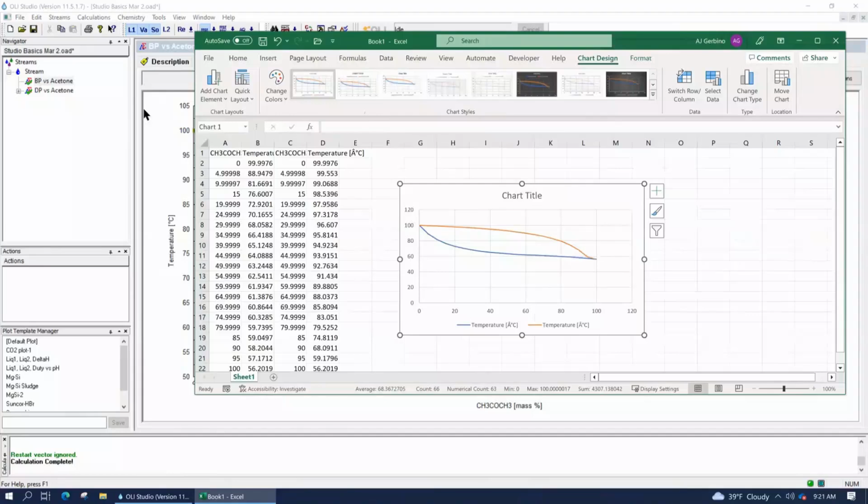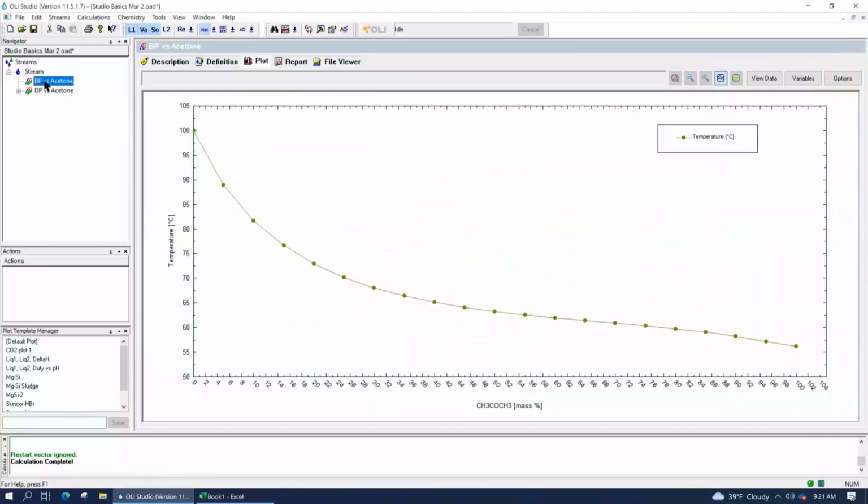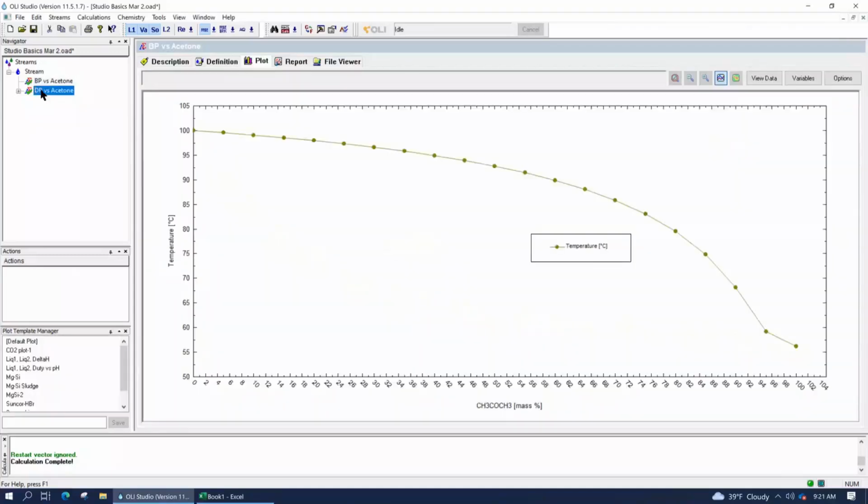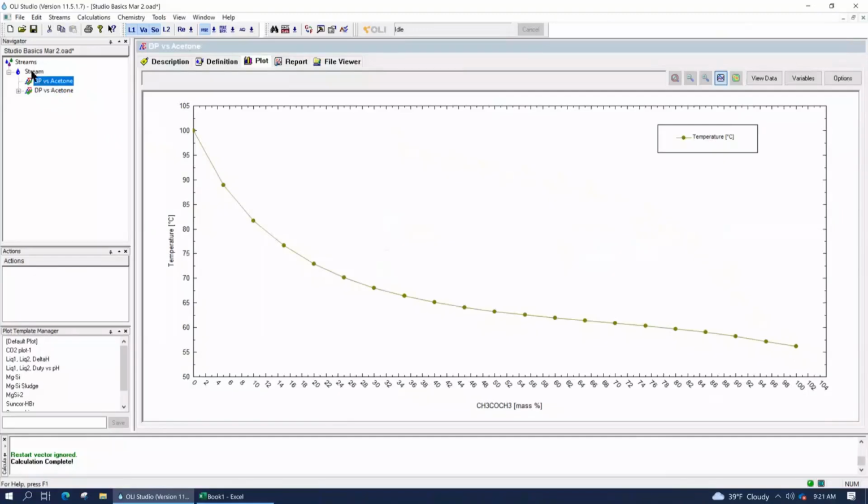Okay. So the teaching point on that was that one, you can create phase diagrams, binary systems, even ternary systems if you need to, with the software. And you can copy and paste calculation objects in order to duplicate them inside a given stream or even across streams. And then lastly, you can copy and paste your survey results from the plot itself into an editor of some kind.